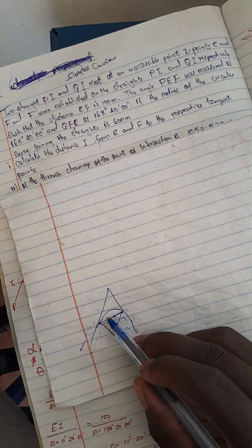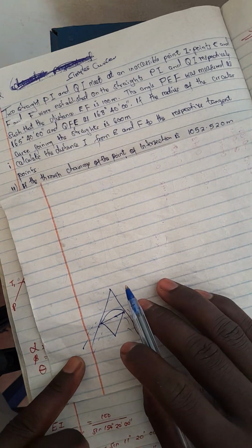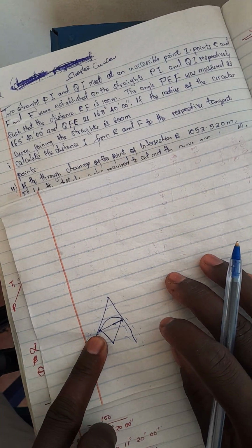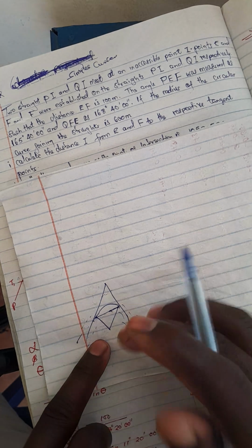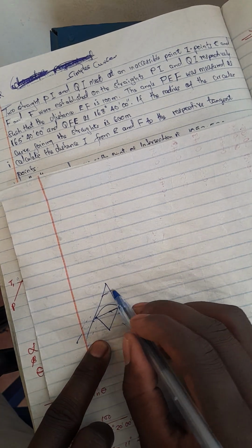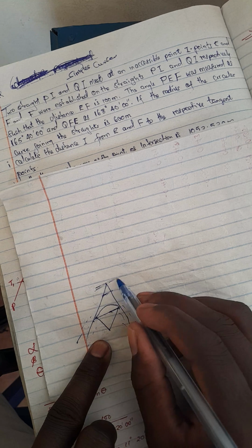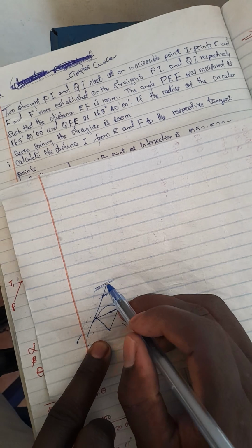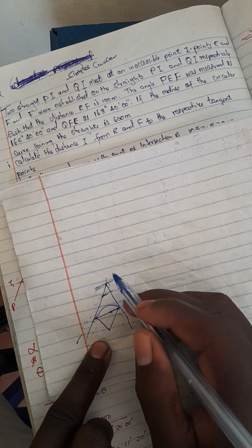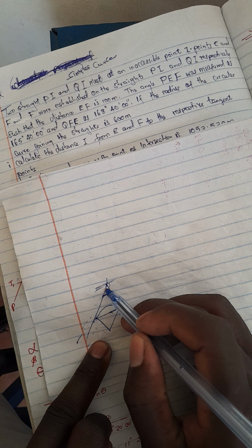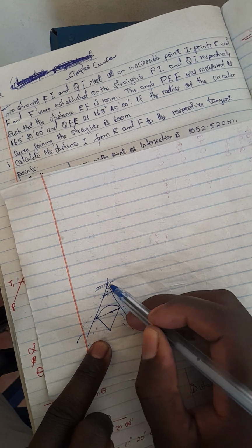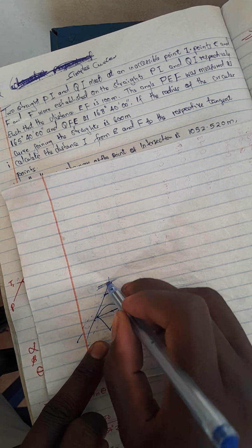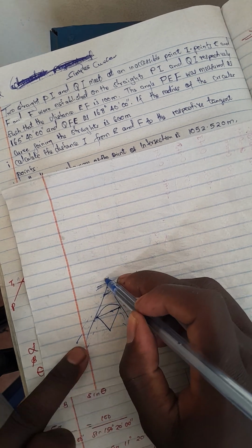So now our question is an application where an obstacle is here. For those common questions, we normally have the deflection angle. We can get the angle of intersection, which is here. The deflection angle is here. We can determine the chainage at the point of intersection, which is here.